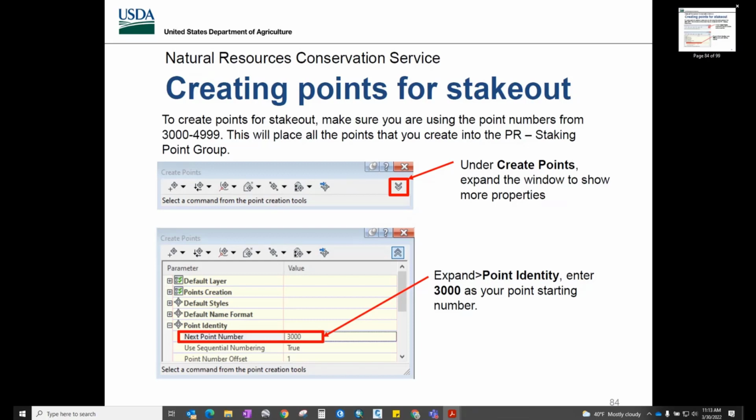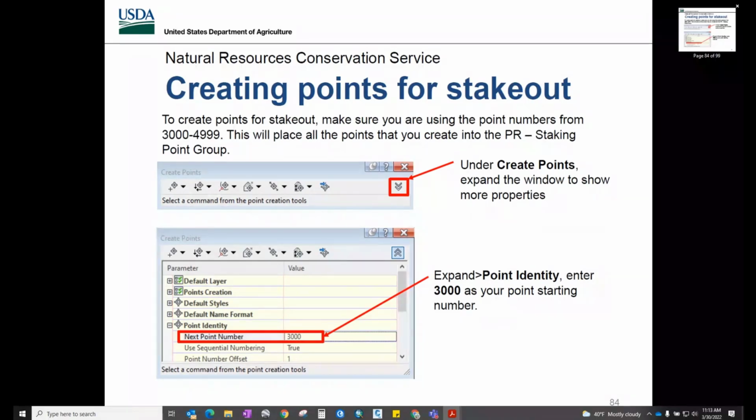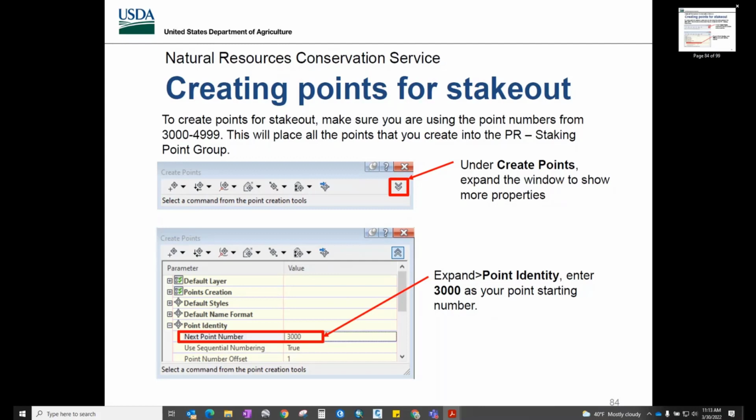I always try to use it as verifying. We're verifying the elevation, and we just have to make sure at the time of the pre-construction meeting that if a contractor says, can you stake this out for us? Sure, we can stake it out, but make sure that you double check our elevations, because we're not held responsible for those elevation mistakes. If we make a mistake, everybody's human, we make mistakes. But if we set those grades and they go off of those grades,